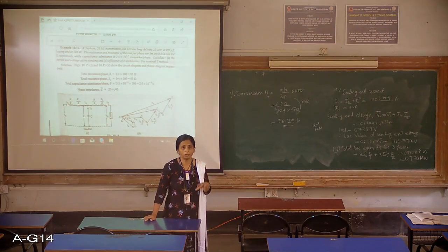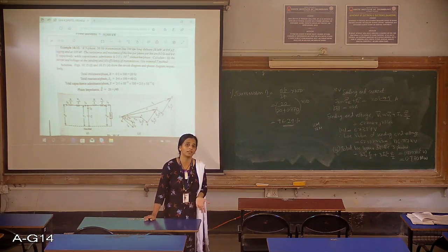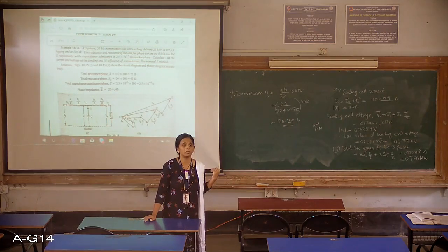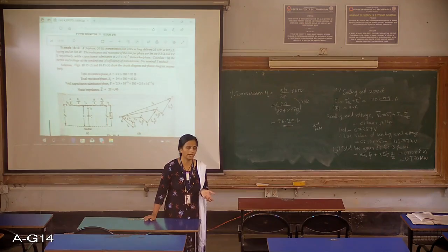So with respect to the pi model, you will be evaluating the bus admittance matrix Y bus in the further semesters to come. So please pay attention to tomorrow's method, and then we'll take up some problems on the pi method. Then we'll briefly discuss what long lines are, okay, we don't have any derivations for the long lines. And then directly I will start with what is meant by the ABCD constants and what are their values for short line, medium line and long lines. Okay.